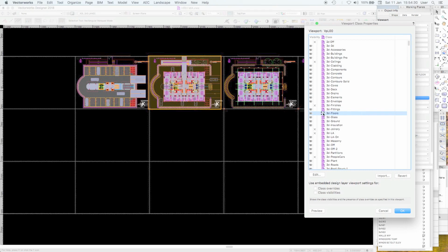It tells you when a class has been edited. Use viewport specific class definition. You want to see all the ones like that, you just double click on the icon at the top. And so I've got, in this viewport, 1, 2, 3, 4, 5, 6 that I have edited, which overrides the global class definition. Now, this only works if the objects have their attributes set by class.